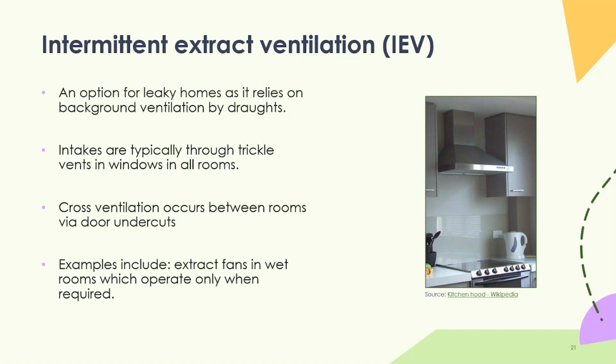Next point on there is intakes are typically through trickle vents in windows. So that is a common counterpoint to the extract ventilation, is that you would have the trickle vents open, just allowing for that background ventilation in most rooms.